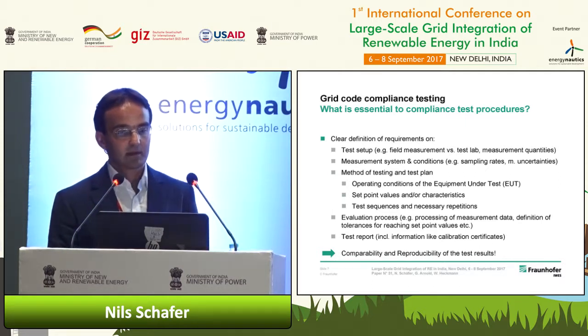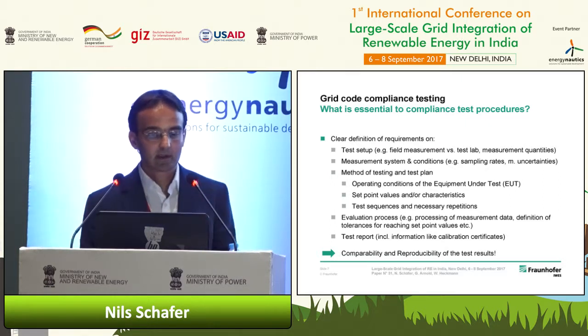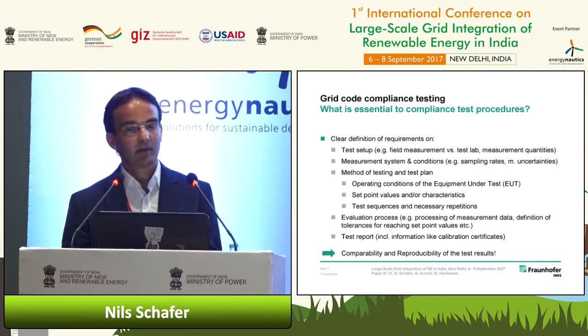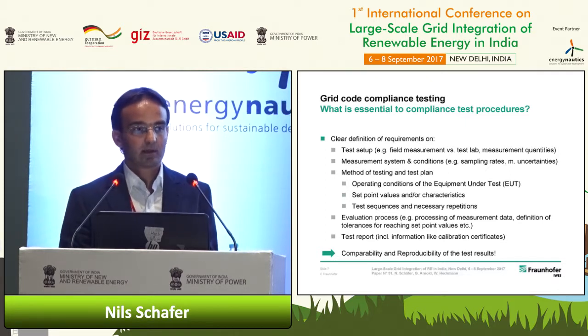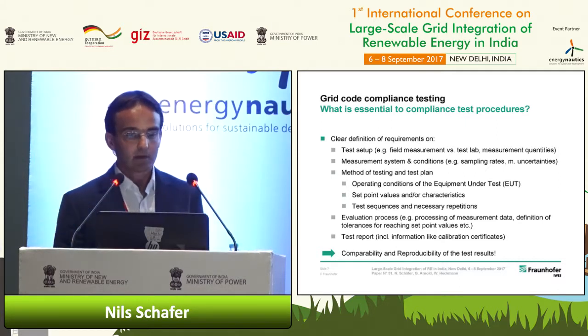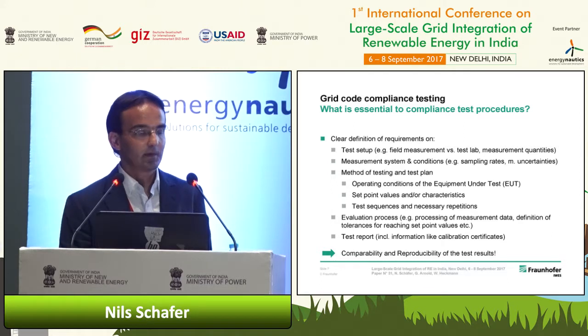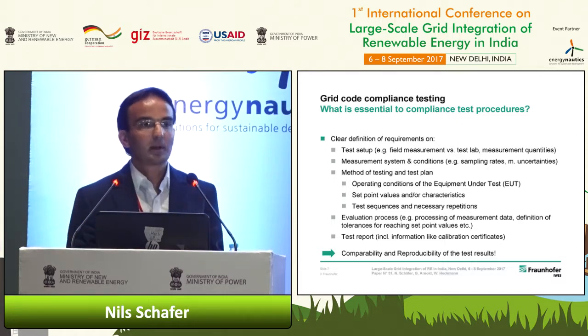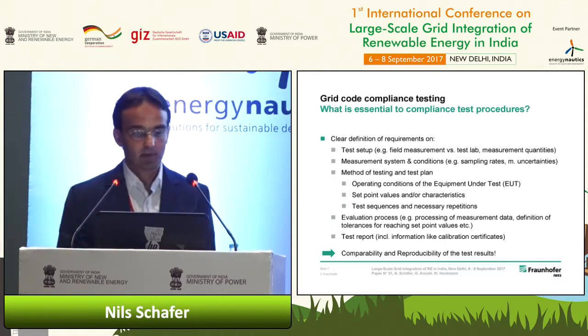It's also very important to define clearly the evaluation process: how the measurement data is evaluated in the end and what tolerances shall be taken into account. I mean tolerances for how close you come to set points and the time it takes to arrive at set points.